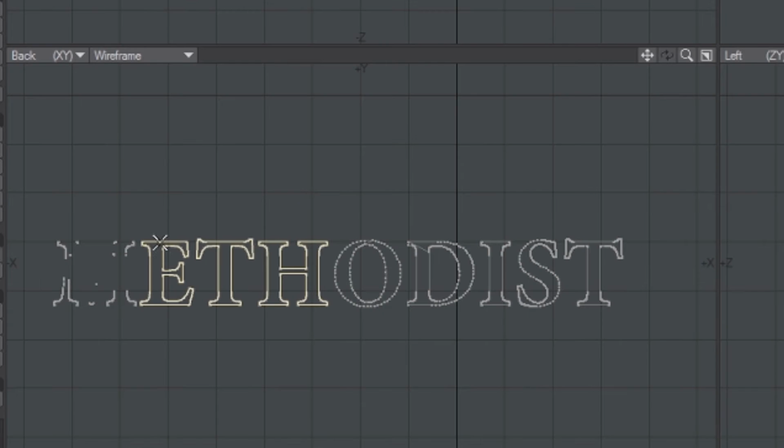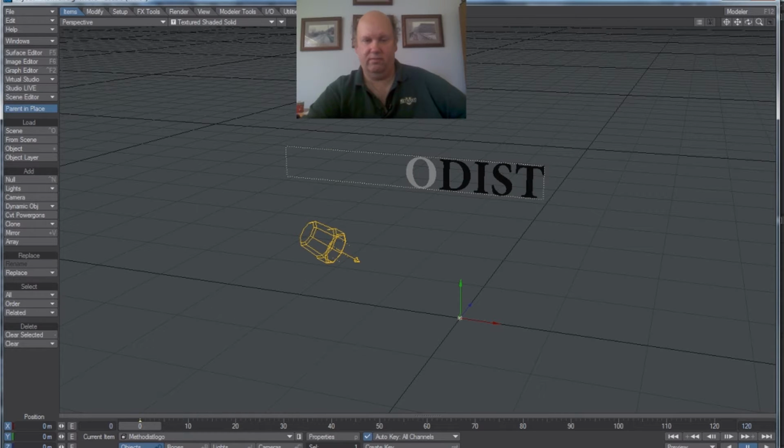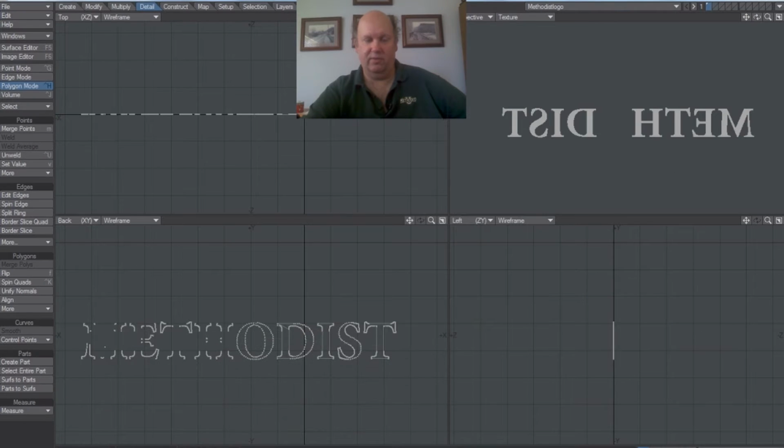And then we're going to deselect these polygons, and you'll see it appears to have destroyed the polygon surface, but it really hasn't. We save the object that way, and we go over to Layout. We can see that they don't appear to exist at all, but believe it or not, that's an improvement. If we select polygons again, including that one, I hit the F key, that will flip the surfaces around.